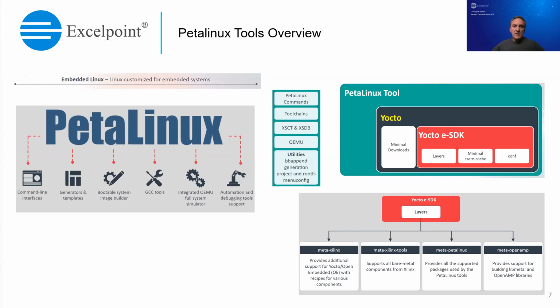Petalinux, on top of that, includes utilities that are not found in the Yocto toolset, such as the scripted command line tool and the ZYNQ debugger, a device tree generator, and other tools used for build and deployment. The tool chains used by Petalinux are based on GCC and Linaro external tool chains. Petalinux uses XSCT underneath, that interactive and scriptable command line interface, which supports creation, configuration, as well as building all the common software projects. And it also, as mentioned, includes the ZYNQ system debugger.